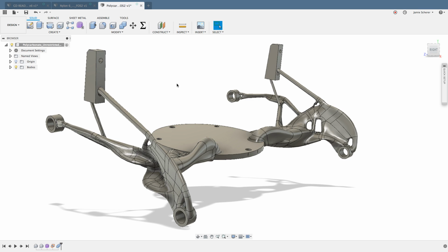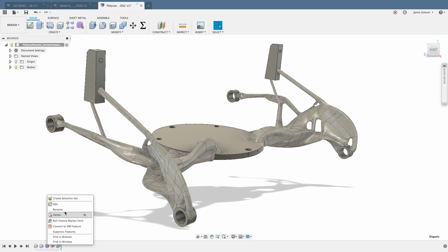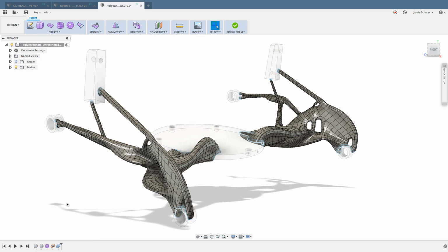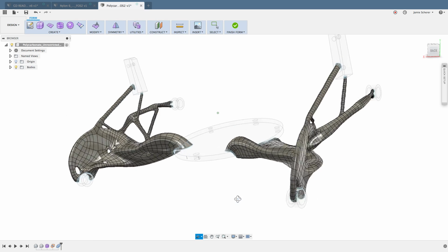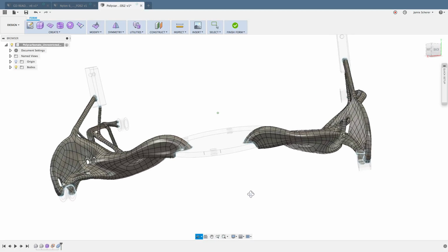Now, a timeline for something that we didn't create, something that was generatively created, will automatically appear when you download the results from the Generative Design Workspace. But most importantly, you'll see that all of the areas in the middle are going to come in as T-spline geometry. So if we double click on the sculpt object in the timeline and edit it, you'll see that I now have editable T-splines that I can begin to work with.